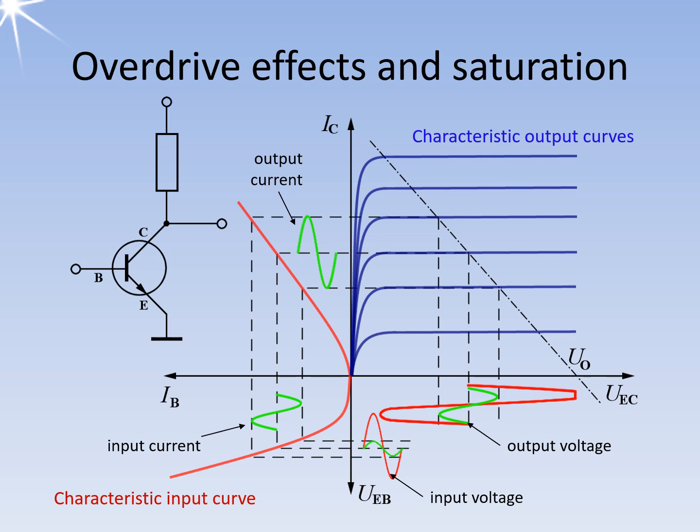In radar receivers, therefore, there is a series of measures to control the gain. The most common measures are the logarithmic amplifier and some circuits of sensitivity time controls. All these measures must be well defined so that the radar signal processor can follow the changes in the signal processing.